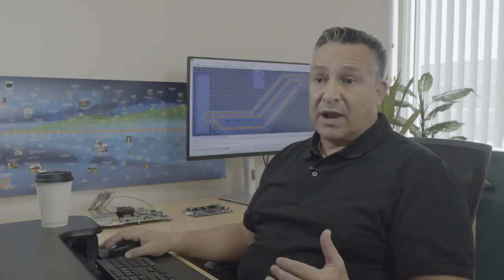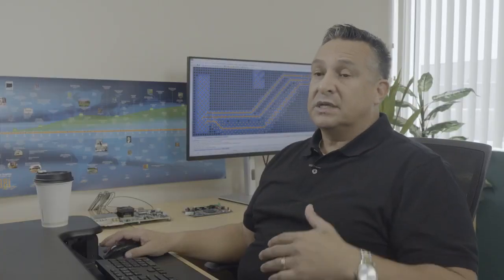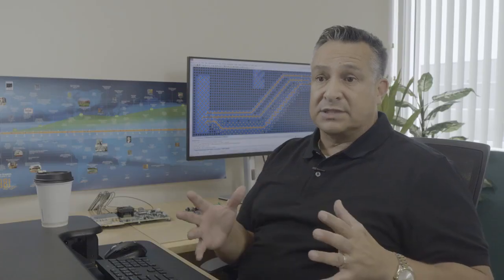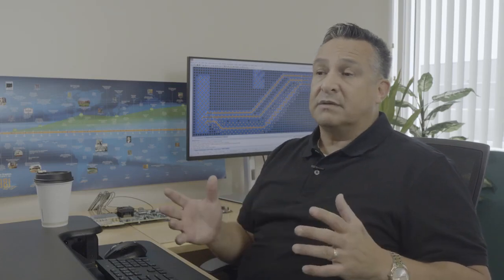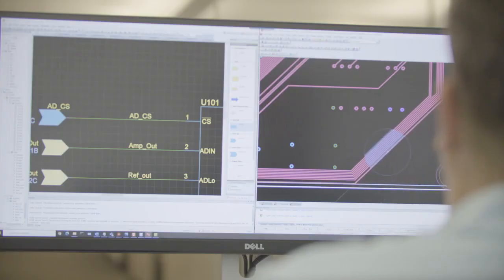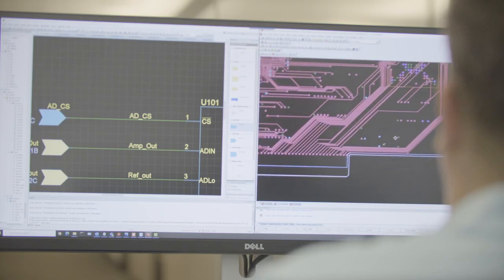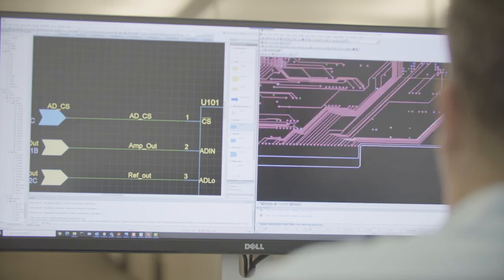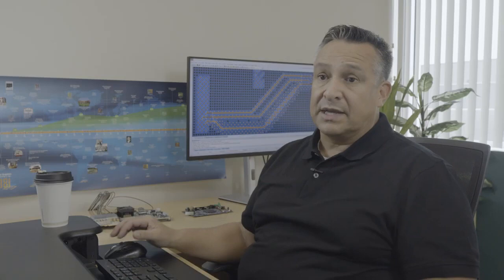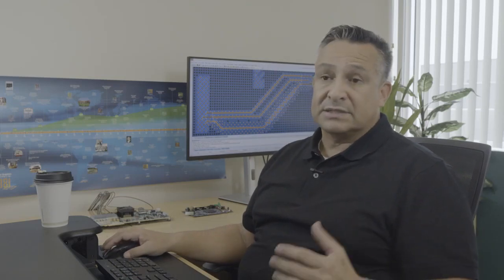When we talk about best practices and how to improve or optimize, we'll first look at analysis. You've got to account for the analysis when you're first planning your projects. Don't skip it. Don't eliminate the analysis simply because you're trying to reduce project schedule and costs, because I guarantee you it's going to bite you in the end, especially if you're doing complex high-speed or RF microwave designs.